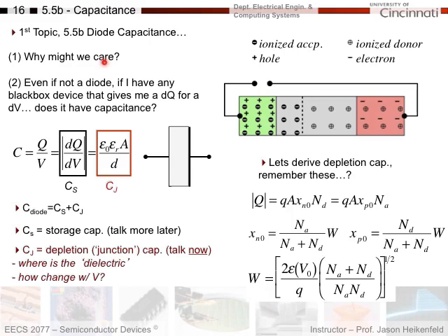So you can look at the charging and discharging time, and ultimately you can never run a circuit faster than its RC time constant, right? How long it takes to get charged through the resistor to charge up a capacitor. So this is useful in understanding how fast we can run circuits with diodes. The other reason it's important is every time you charge and discharge a capacitor, you consume electrical power, right? And so it's also important to understand capacitance from the perspective of electrical power consumed.